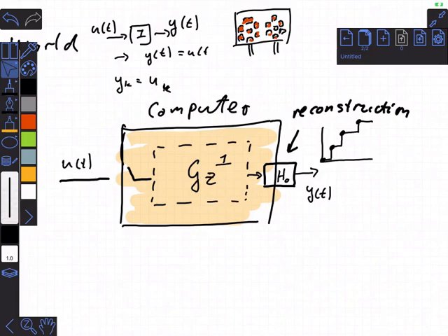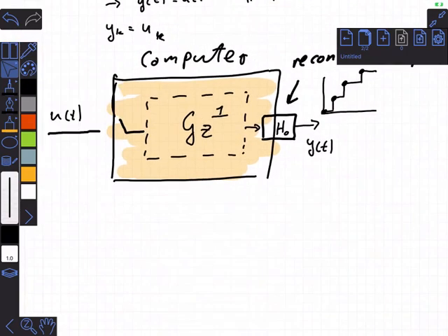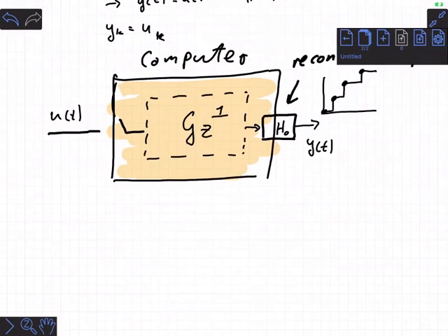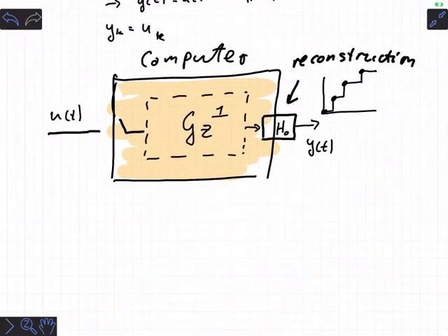So once we start talking about reconstruction, and definitely once we talk about reconstruction within the context of control where low latency is very important, why? Because I want to act on the reconstructed signal. I want the reconstructed signal to operate things in the world, to move valves or open up the electricity flow or whatever.